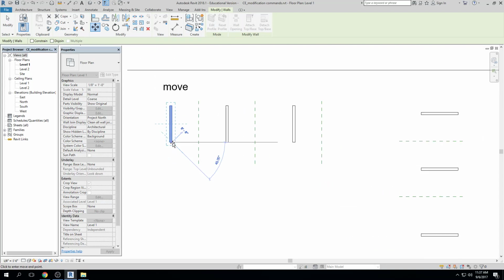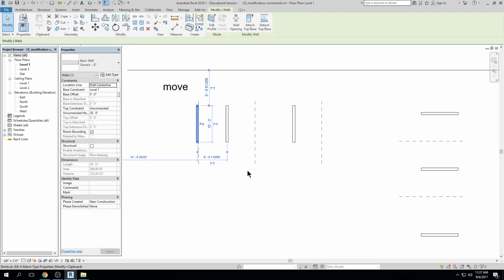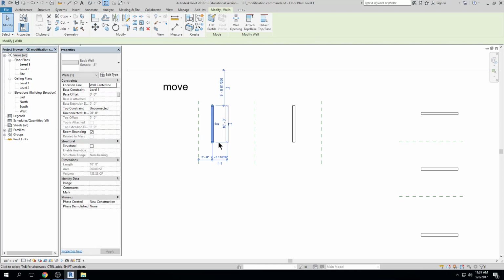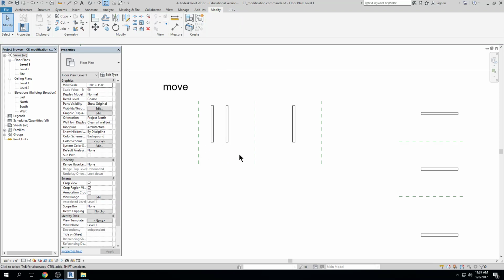Click to establish a point on that object or near that object that then we can move the object to something, click, or MV, click, and I could type in a dimension, something like 4 foot, and it moves 4 feet, right? This is just like AutoCAD. The only difference between AutoCAD and Revit in this instance is that you generally want to click on the object first and then perform the operation, right? I can still click on move and then click on the object, but it feels weird because then I actually have to hit enter, and it's very counterintuitive in Revit.